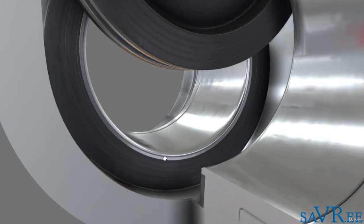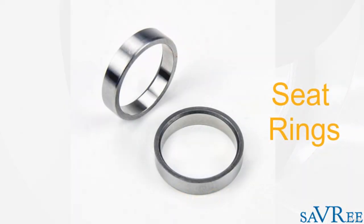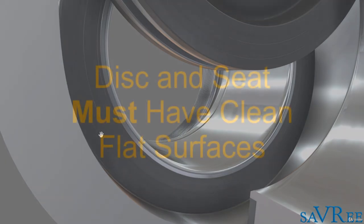While we're down here, we can have a quick look at the seat. The seat, this area around here, is normally either part of the body, such as a flat machined surface, or we'll use seat rings. And seat rings are usually metal rings. The advantage with these seat rings is that if the seat becomes worn, you can just change the seat ring. So seat rings make it easier to repair a valve, such as by repairing the seat if it's leaking, by simply swapping the rings out. In order for the valve to seat correctly, we need both the disc and the seat to be machined flat so that they can press against each other and form a seal.